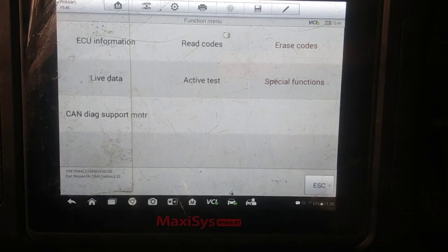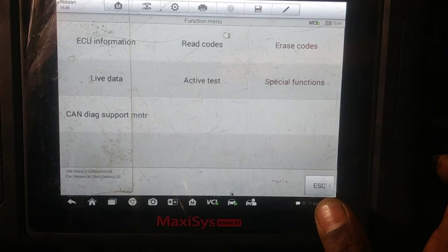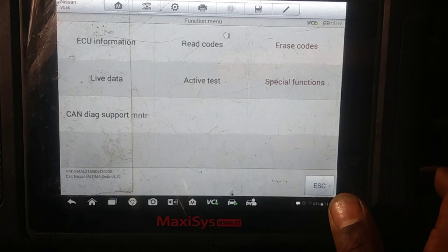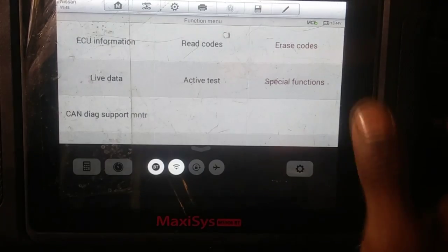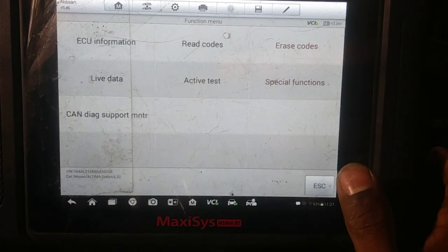So you have to have either an oscilloscope, some other method of accessing some type of visual abilities to see what's misfiring. Air-fuel ratio sensors may help, but you know, you can look at them, assuming you can get it to misfire and catch it at the right time, like I did on my older videos. But I didn't utilize that resource. That's usually my last option, especially if I don't want to go through the extent of putting an oscilloscope to the signaling wires.